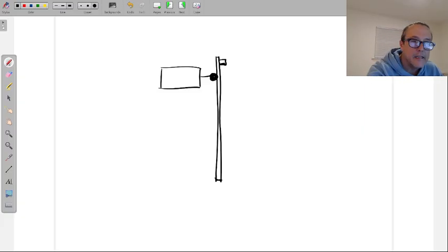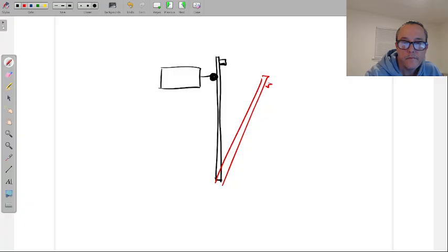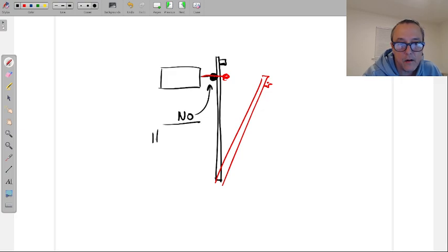So we designed it to where the second they opened this door, this limit switch would pop out and it would kill the machine. All right, it would stop the machine instantly. So this is a normally open, but it was being held closed.